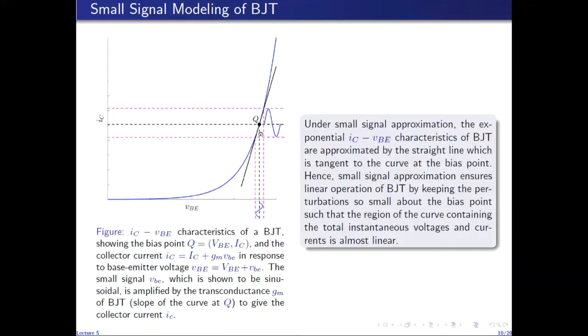So again, same graphical interpretation: the small signal ensures that the transistor operates within the portion of the nonlinear curve which can be approximated with a straight line, which is tangent to the curve at the bias point. This is what makes the output approximately a linear function of the input.